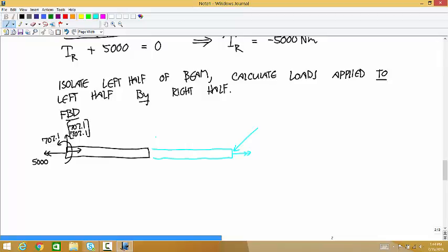And so the way to think about that is this contact point between the part we're choosing and the part that we're not choosing is a fixed joint. And so the types of loads that can be applied here by the stuff in blue are all the loads that a fixed joint can apply. So that is a full force vector.